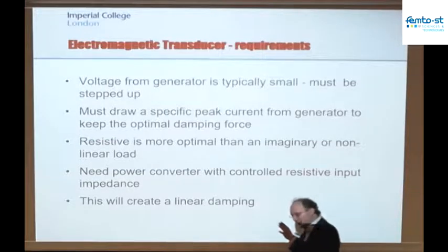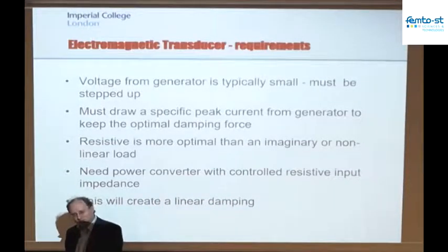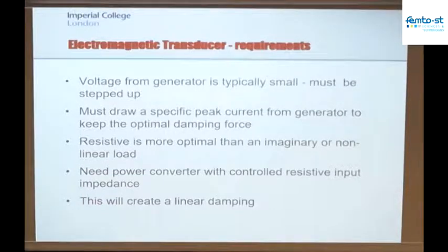So I'm going to analyze my mechanical system. I'm going to say, okay, in this operating mode, this is the size of the harvester, this is the excitation from the mechanical vibration, and I can work out the optimal force to maximize the power generation capability of that mechanical system.